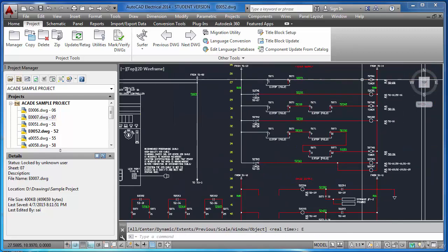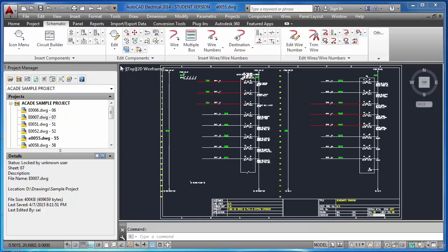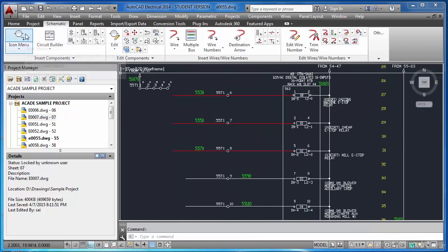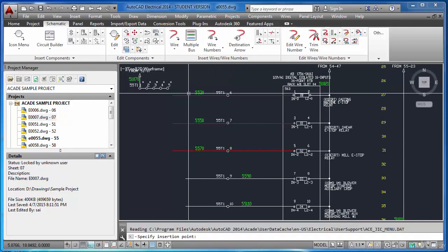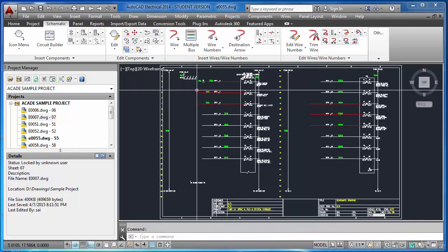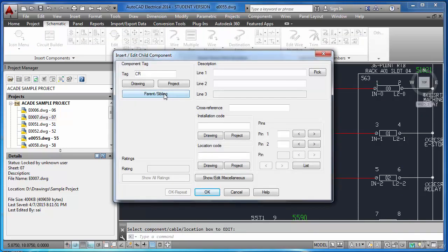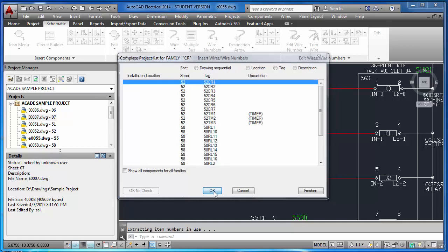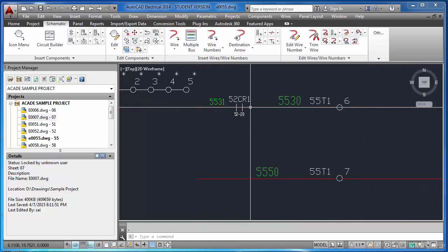So now first I will put a contact here in this digital input card. With the IO description, I know the first relay should come here. The feedback of the relays, the NO contact, I am going to put here. Project 52 CR1. I know this was that relay. Okay, 52 CR1, it is here.